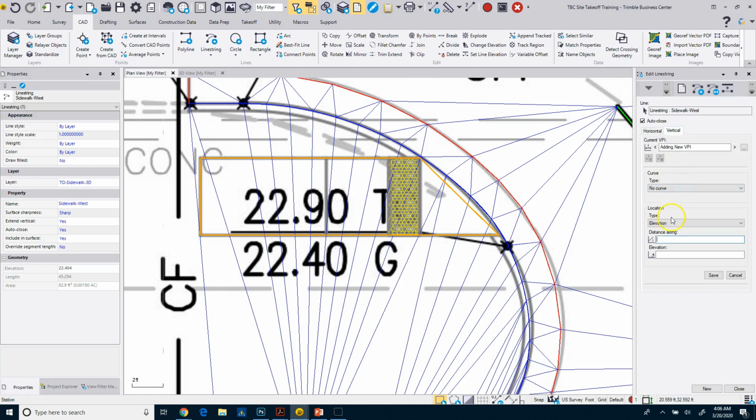So vertical, my outgoing slope, or incoming slope, sorry, at this particular point is going to be, let's just go 5%. We can go 8, but let's go 5. This one here, my incoming slope, I'm just going to set it to 2 because that's my max. This one here, I can also set to 2. Or actually, my incoming is going to be -2, only because I'm cross sloping it and draining it that way. And then let's see this guy here.